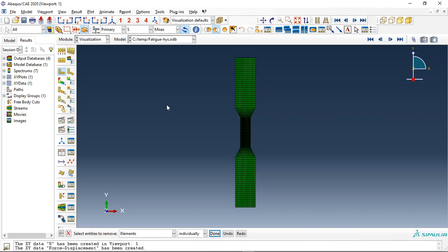Today we model fatigue analysis of a steel specimen, a steel part here. Typically on our website we use the Paris law to model cyclic loading. We're using the direct cyclic step in Abaqus. Under the cycle, we could see the damage which happens based on the damage law for the Paris model.